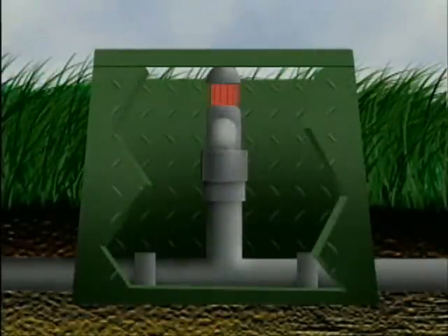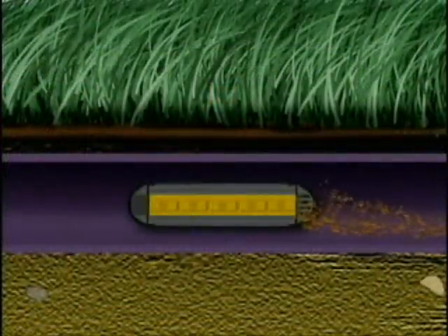At the end of the dosing cycle, the valves allow air to enter the drip laterals as the water slowly drains from the emitters. Without air relief valves, a vacuum develops, causing soil to be sucked into the upper emitters and plug them.